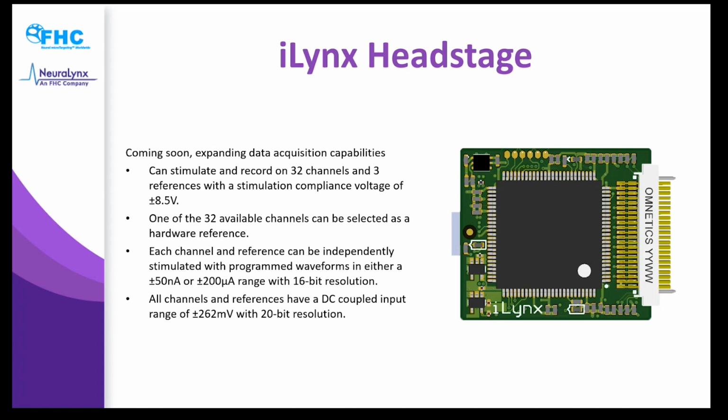And then all of these channels and references are DC coupled, with an input range of plus or minus 262 millivolts with a 20-bit resolution. So this will be a great increase to the current capabilities of stimulating head stages that are out on the market now.